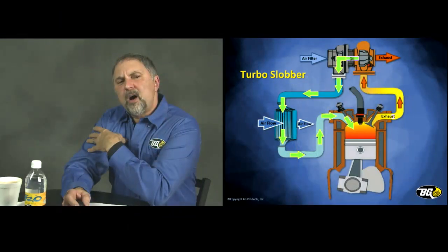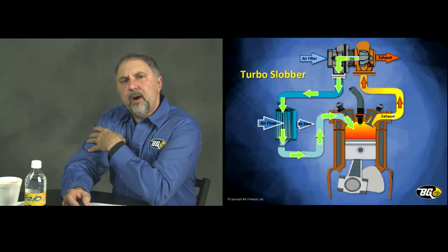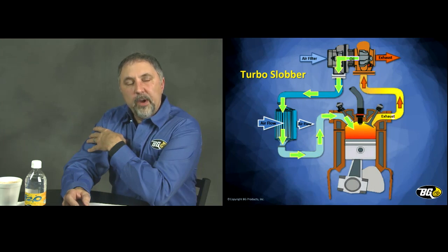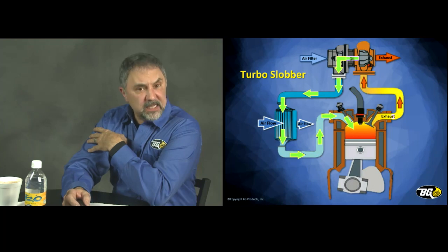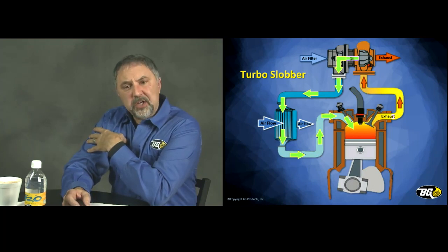At this point here, I'm often asked, hey, can our 9300 or the 9255 clean turbos? We never send chemistry through the intake side of that turbo. We always go after the turbo. However, on the exhaust side, you notice it has to go through the turbine wheel. Yes, you might be able to clean some of the soot off on the exhaust side. Is it designed to? No, but I've seen it happen. That's a question I'm often asked.